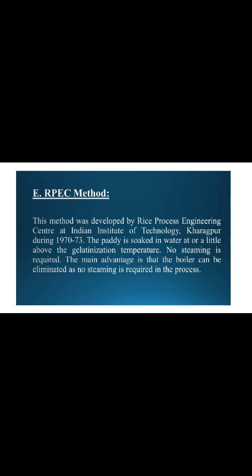Then the RPC method. This method was developed by the Rice Process Engineering Center at Indian Institute of Technology Kharagpur during 1972 to 73. The paddy is soaked in water at or a little above the gelatinization temperature. No steaming is required in the RPC method. The main advantage is that the boiler can be eliminated as no steaming is required in the process.